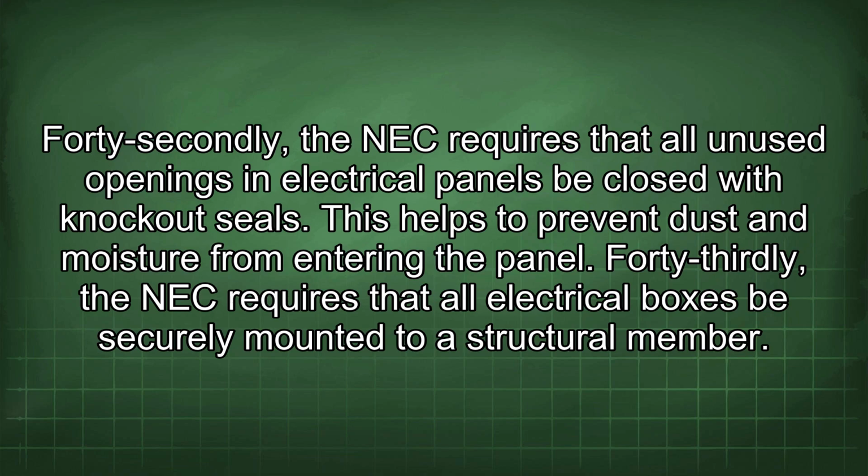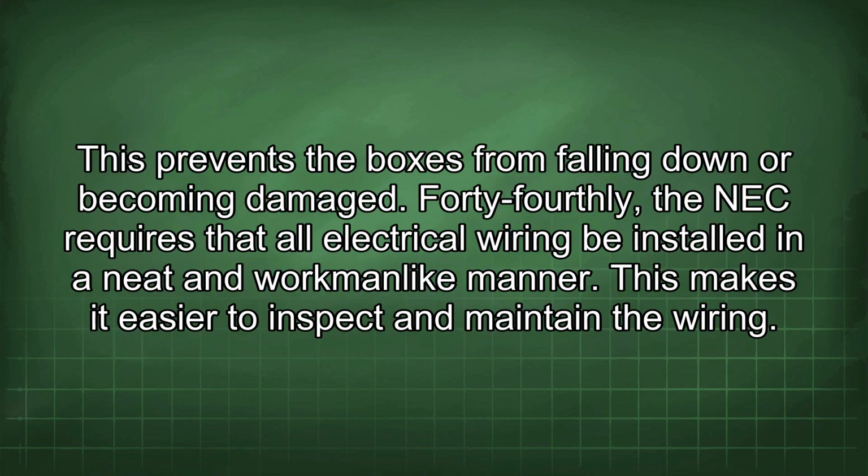42ndly, the NEC requires that all unused openings in electrical panels be closed with knockout seals. This helps to prevent dust and moisture from entering the panel. 43rdly, the NEC requires that all electrical boxes be securely mounted to a structural member. This prevents the boxes from falling down or becoming damaged.